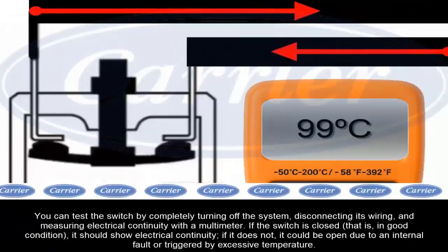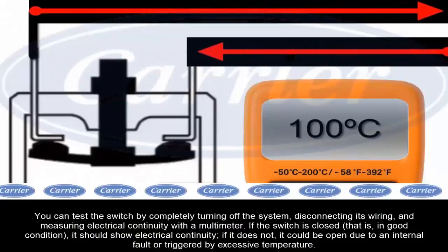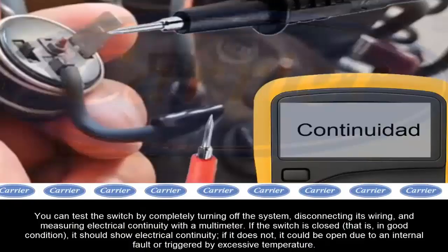You can test the switch by completely turning off the system, disconnecting its wiring, and measuring electrical continuity with a multimeter. If the switch is closed, that is, in good condition, it should show electrical continuity. If it does not, it could be open due to an internal failure or activated by an excessive temperature.